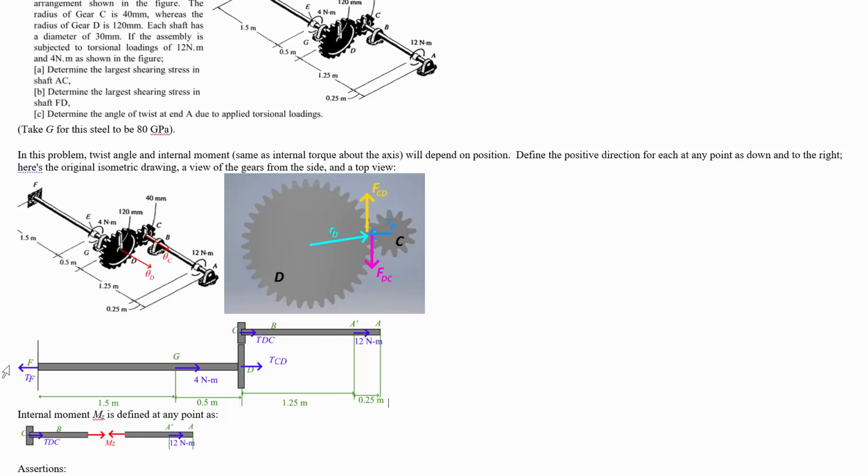So we have no displacement over here at point F, and we're going to have a reaction moment applied by the wall because it's a fixed support. So A is a pin, can't apply a reaction moment, but F is a fixed support, so it can. We'll draw its reaction here as TF, like a reaction torque. Yeah, it's a pure moment that it's going to apply, but it applies a torque as well, by it being a moment. A moment is just a special case of an applied torque.